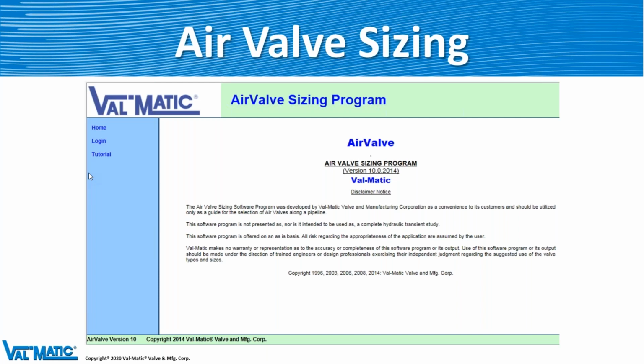So our air valve sizing program, now this is the link that I'm going to send you tomorrow. It's for this program, and it's also on our website. You can go there and fill all the details out. What's nice about this program is it will ask you 101,000 questions, but it's to properly help you size air valves. Pressure, how many pumps you have, is it going to be close to a pump, how many feet of pipe, how many high points, the size of your pipeline, those kinds of things.